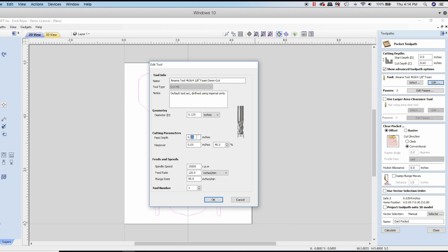And if I try to cut too deep, then there's a chance those peels will wrap around the end mill, and that'll cause a burning effect on the edges, and I don't want that. So to avoid it, I keep my pass depth at no more than 2 times the diameter. That creates smaller peels, and then I always keep the dust collection system on, so when they break free, it draws them away from the end mill. Okay, so we're going to use pass depth to 0.25.